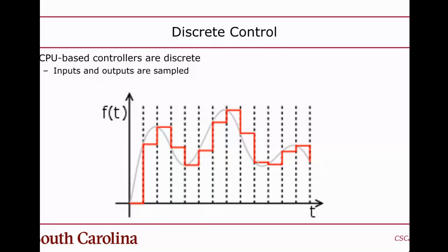And also keep in mind that, as I mentioned at the beginning of the class, we're targeting cyber-physical systems, which are usually low-cost CPUs. They're not often that fast. And not only that, but you may want to run other things on them too. So you might be time multiplexing the CPU itself, so you may not necessarily have the entire attention of the CPU. You may be only coming back and issuing control signals at a relatively low rate, because you're having to do other things on the CPU as well. So these are all things you need to consider.